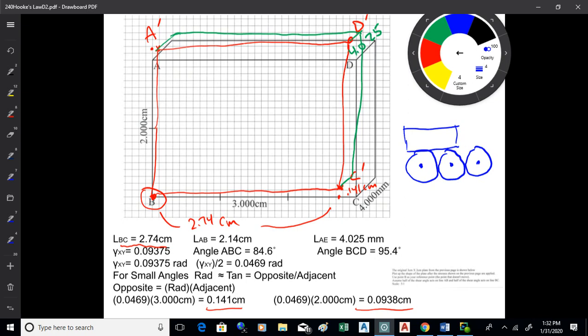So that's an example of why you might be interested in this, especially in the mechanical world, because if you start building machines where one moving part interacts with another moving part, you know, that's when things get a little interesting there. If you've taken apart an internal combustion engine, there's rings around the piston that have to seal right on the cylinder walls, and they're flexible, right? Because there's all these heat changes going on in there, so there's got to be a little bit of slack in there, but there's also that need to get a perfect seal so that you get good compression and all that. So that's one solution to that.